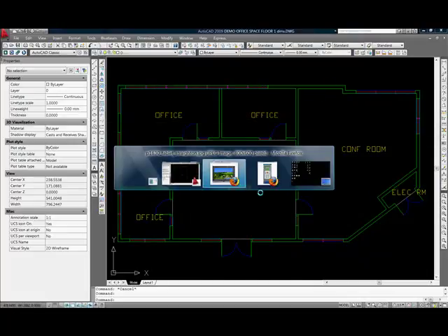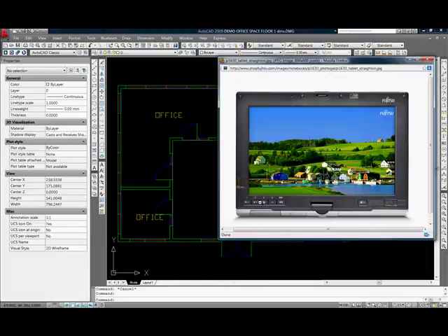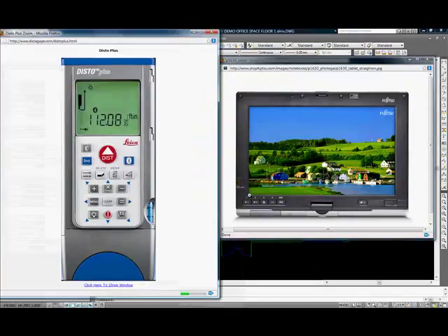So LTS runs normally on our pen tablet computers. Our surveyors carry a Fujitsu pen tablet computer, as you see here in the picture, and it would be running our survey software. And it is connected by Bluetooth to a laser disto, which is what you see here. This is the Disto Plus. And every measurement we take, anything over 6 inches, we laser measure. Anything under 6 inches, we record manually with a tape.